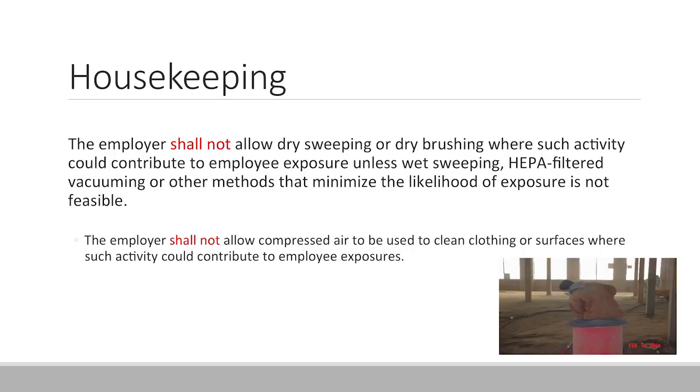Housekeeping. Employees shall not dry sweep, dry brush, or use compressed air where such activities could contribute to employees' exposure to silica dust. Written exposure control plan. Employers must have a written exposure control plan for every silica creating task. Our plans will be located on field tools.